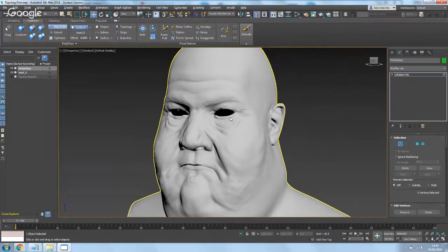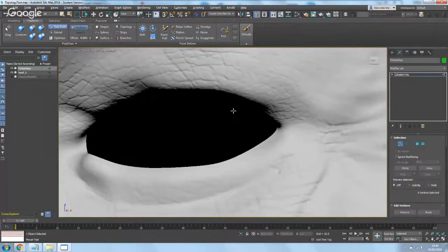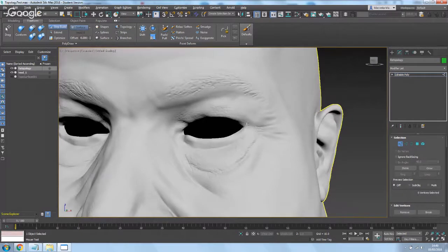So click on step build, and then zoom into the first area that you want to draw the polygons onto. So for me, I'm just going to quickly draw around this eye. Now, before I start doing that, the new mesh that I'm going to draw will be sitting on top of the high poly model. And depending on how high or low this offset number is here, depends on how far away the new surface will be from the high poly surface. So for this model, I've set it to 0.2. For you, you may want to adjust and adapt this, but I'll show you how you can change that on the fly later.